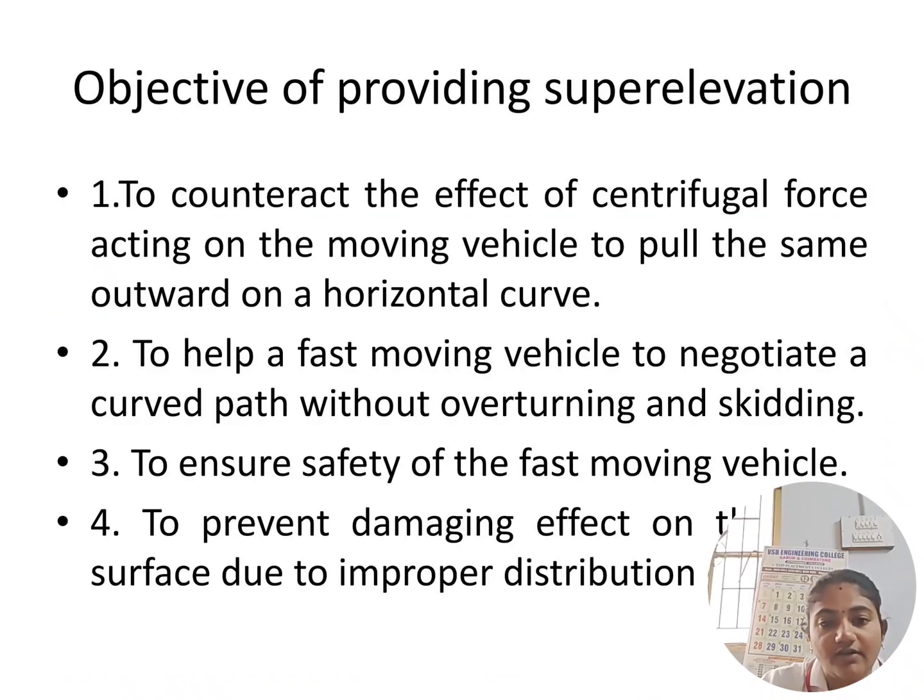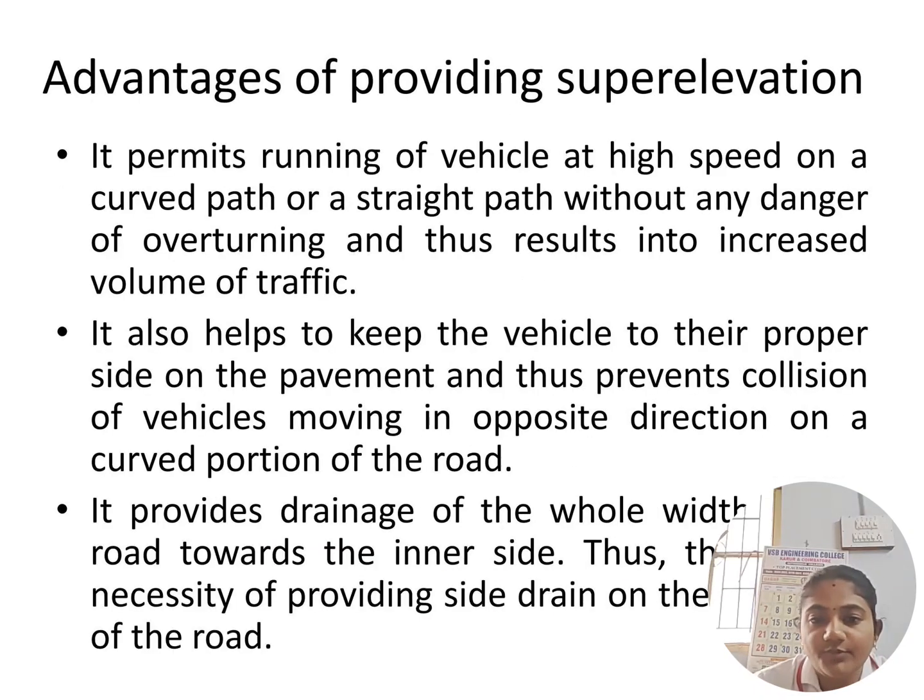Objectives of providing superelevation: to counteract the effect of centrifugal force acting on the moving vehicle and to pull the same inward on a horizontal curve, to help a fast moving vehicle negotiate the curved path without overturning or skidding, to ensure the safety of the fast moving vehicle, and to prevent the damaging effect on the pavement surface due to improper distribution.